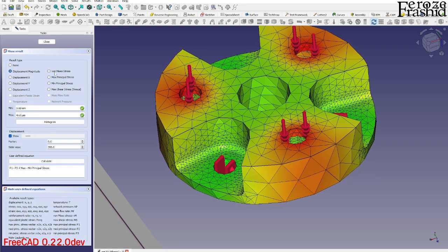And let's take a look at how much stress it's creating. It's creating 38 MPa, which is way below the allowable stress. The allowable stress is the yield strength, which is 240 MPa. So it is way below the capacity of the material, but this displacement is very insignificant.